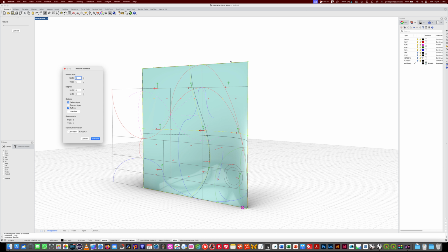If I want several columns, I'm dividing in the bottom, and the bottom is X. When translated, it will be U. So I'm going to pass from 5 to, let's say, 9. Okay, I can preview. Eventually I could have more points, so I will put 11. Okay, so this rebuild allows me to see.